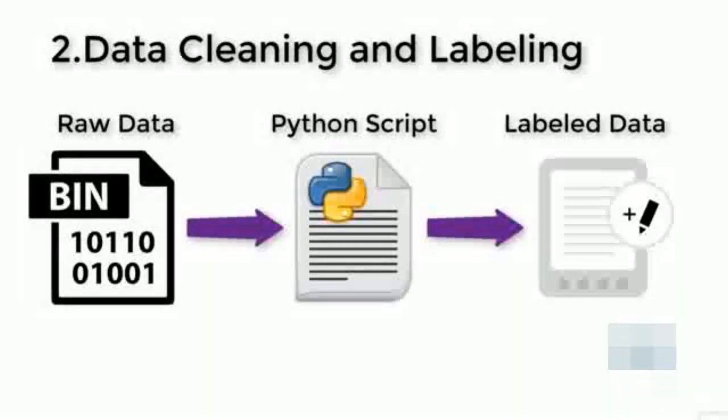It can be in hex or binary form or not arranged in such a way so that we can train the neural network directly on it. We need to rearrange this data according to the expectation of our neural network model. We may need to apply some high pass or low pass filters to mitigate the noise from the data.